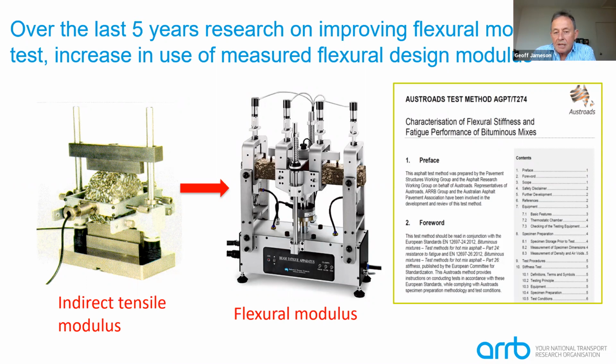How you would translate that to an allowable loading, what the shift factors are between lab and field, has yet to be determined. So there's a whole research opportunity there for someone to develop a process. There's no processes we currently have to translate the fatigue of a stabilized subgrade layer to an allowable loading.